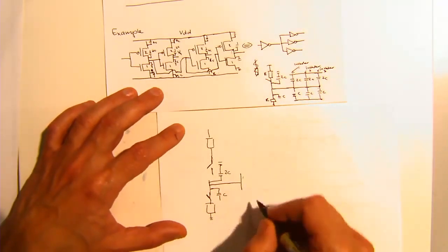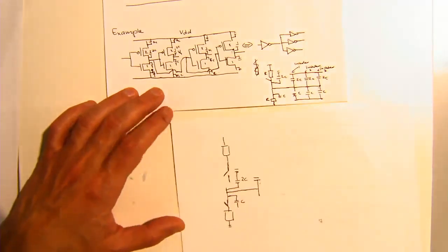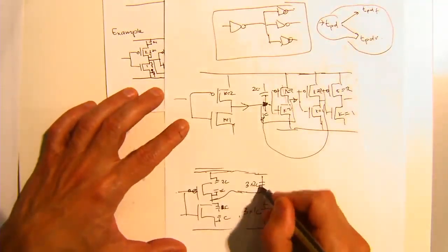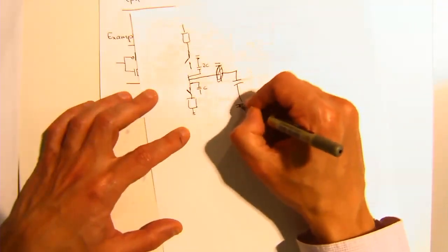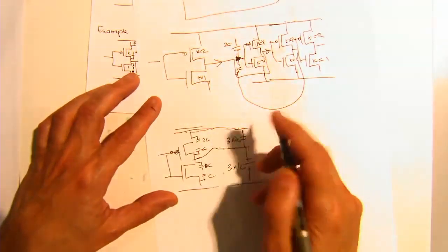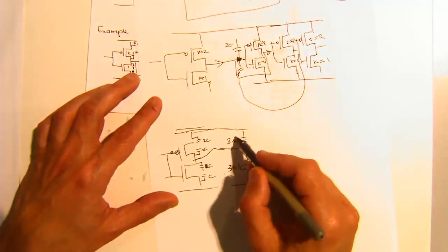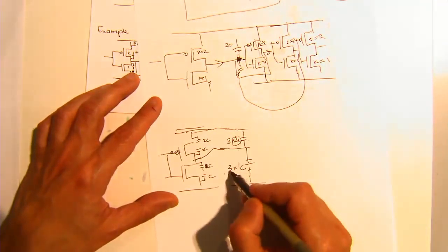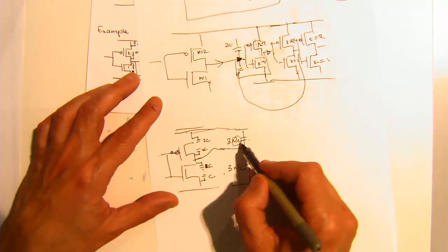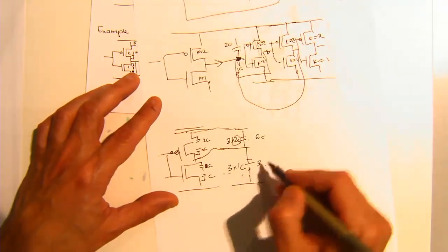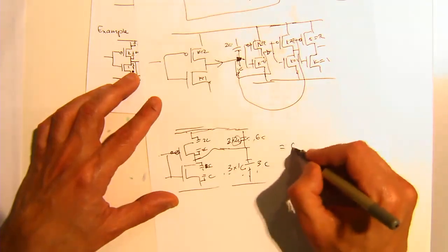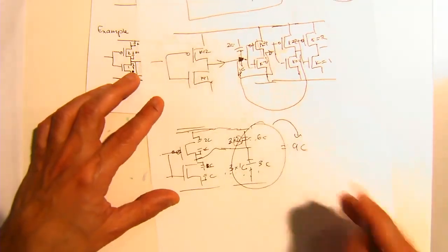Okay. And what we see here is we've got 6C plus 3, 9C, right? So we got 9C here. Can anyone tell me why we have 9C? They're in parallel. So there was 3 and each PMOS had 2. 3 PMOS, so 3 times 2 is 6C, 3 plus 1 is 3C, they're still in parallel, so therefore that's 9C. Okay?